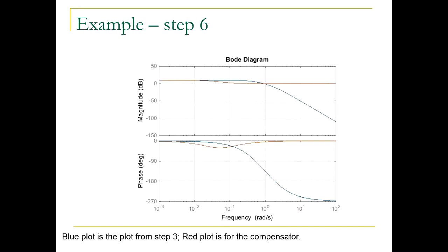So you are looking at, here, so note, blue is going down, blue would eventually become negative, but the red thing would stay positive. So you are looking for the frequency somewhere here where blue would be negative, but the same magnitude as the red positive. Because when you add them at that frequency, you will get 0. And it is at that frequency that, so first you pick that frequency from there, and then at that frequency you need to add these two plots, right?